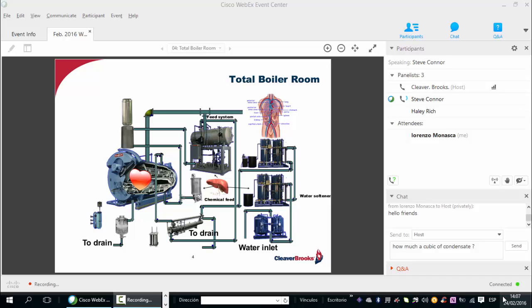The arterial system is the steam supply piping, including all of its components, serving various users. And then the venous system, the condensate return system, returns this liquid gold along with any makeup through the purifiers, which would be the liver, which in the case of the steam system includes the boiler feed system, which could be a vented receiver or a deaerator. Then, of course, the water softener and the chemical feeding device. You can see the liver there in the middle of this screen, and then the arrows pointing to the three systems I just mentioned, or mechanical accessories: the water softener, the chemical feed, and the deaerator.